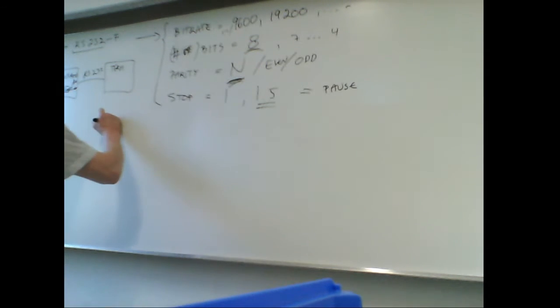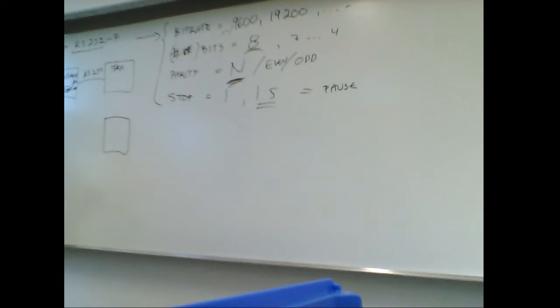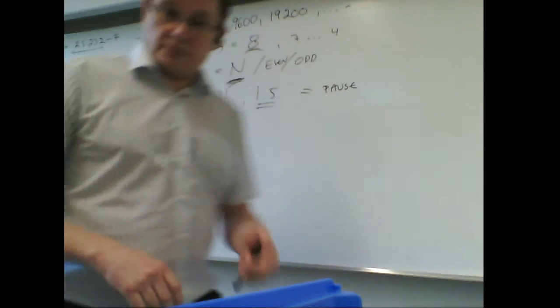And if you have any other similar DTE, data terminal equipment, another DTE equipment here, it also has the TX and RX. So, well, you just need to cross the lines, which you will need to do in today's exercise.